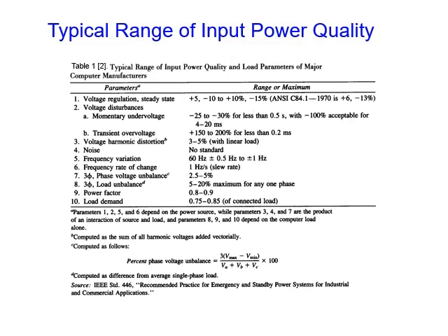If we look at the nameplate of any equipment we deal with, we will find that there are many points related to the power quality. For example, voltage regulation, voltage disturbance, transient, over voltage, under voltage, harmonics and frequency. As an example of frequency variation, the frequency is 60 hertz, but this equipment can handle up to plus or minus 0.5 hertz to 1 hertz.